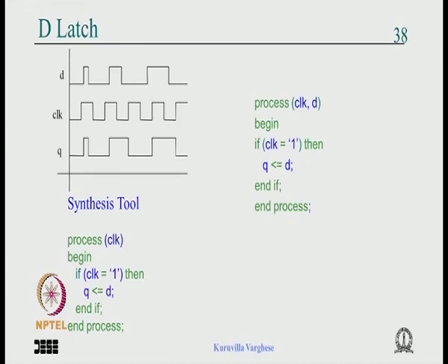We have completed the combinational circuit perfectly, because you know the meaning of with select, when else, if then, case when, loops, all that. Now we are in sequential circuits, where the main things are the registers and the combinational circuit. We have learned how the combinational circuit can be coded, and now we are learning how the registers or flip flops can be coded. So this together should work.